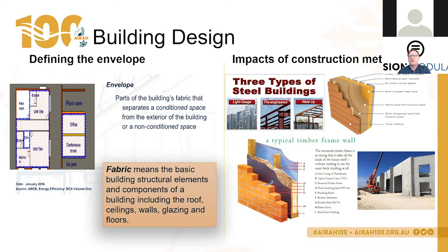The ductwork in the plant room would therefore be considered in all other locations. So if we went back to table J5.5, we would see it's all other locations and we would determine the R value based on that. So the location of the insulation in the building dictates the insulation requirement of the ductwork.